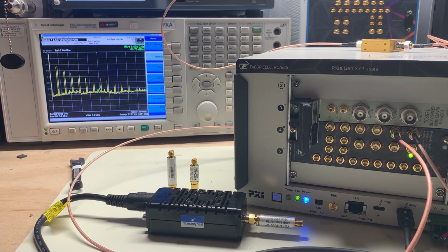So if we want to keep it at 16 bits of vertical resolution, the best thing to do is to use the interpolator. So if I switch the interpolator on and do a by 4 interpolation, you can see we're still at 16 bits of vertical resolution, but I've changed the clock frequency to 4 gigasamples, and we see 75 megahertz plus or minus 4 gigahertz on the spectrum analyzer, and plus or minus 75 megahertz at 8 gigahertz, and one as well to the right there, which is 12 gigahertz.